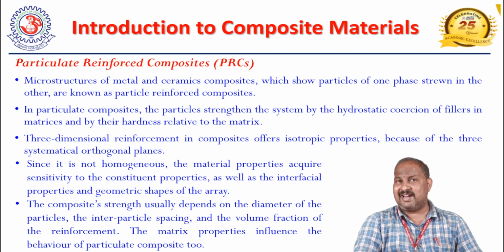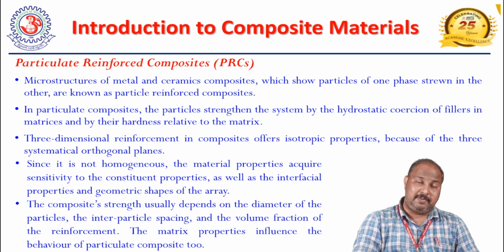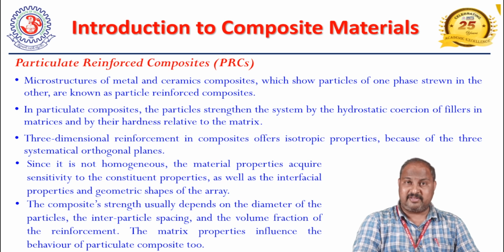Coming to the next category, particulate reinforced composites. Particulate reinforcements are popular in various applications, especially among metal matrix composites and ceramic composites. Here the reinforcements are added in the form of particulates or particles of one particular phase.